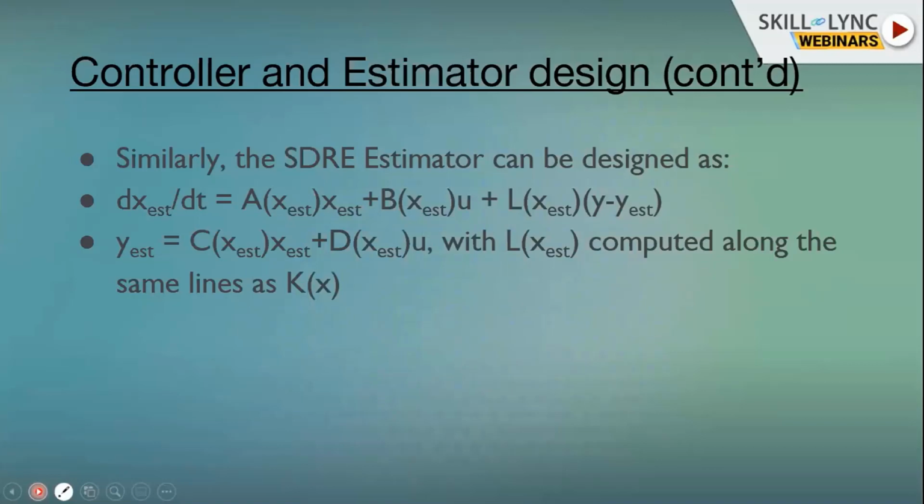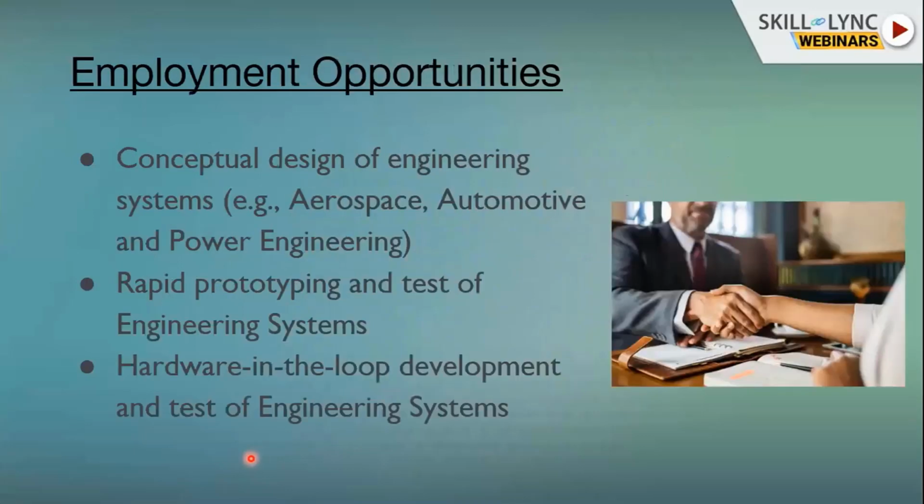And then I'm not touching on the upward V because it involves code. But Matlab Simulink provides Real-Time Workshop, which is used for code generation. So one could replace the modeling blocks with equivalent code blocks and evaluate the controller and estimator designs to see how well they perform when the code is in the loop. So that completes kind of the V model.